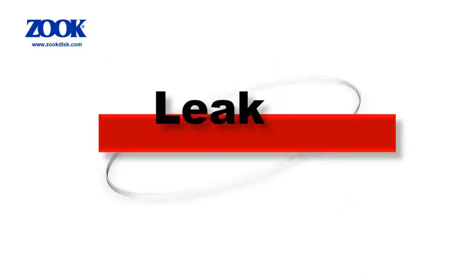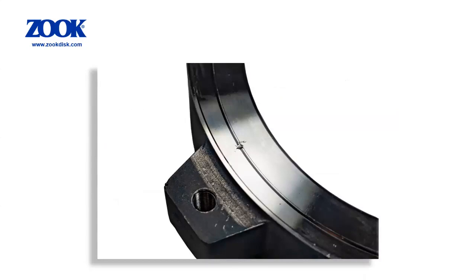There are various methods used to seal the rupture disk within the assembly. This varies from manufacturer, but can include O-ring, pinch point, weld, and metal pipe rings. Care should always be taken when handling holders and sealing surfaces, and they should be inspected every time a disk is changed. Any damage to a sealing surface can cause leaks. In this picture, you can see that the raised sealing bead section of the holder has been damaged, which could create a leak path in the assembly.